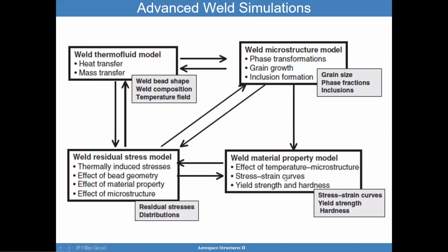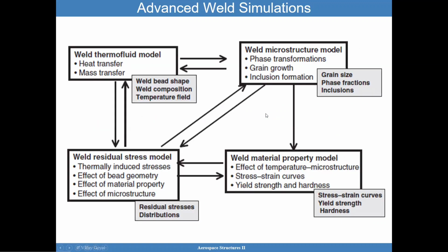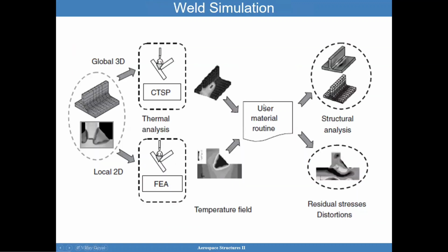You also have the idea of incorporating stress strain curves into the modeling. Weld simulation can also be as complex as incorporating finite element models where you do thermal analyses. You have material subroutines that model a lot of these transformations we're talking about, and then you can determine how residual stress distortions are occurring. And then you can also do structural analysis to incorporate other kinds of loads.